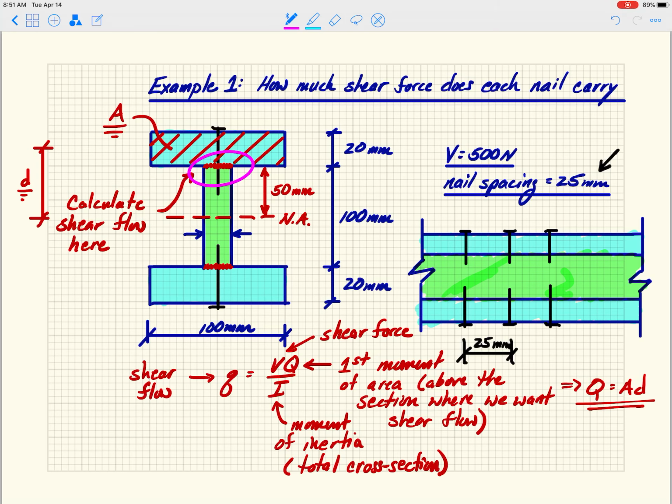I can put angles maybe on the outside here, and bolt through. There's a lot of different ways you can connect these elements. But if I don't make sure that I transfer this 3,704 newtons per meter, what I'm going to get out of this cross-section is what I'm going to call non-composite behavior, and I'll describe that in a second.